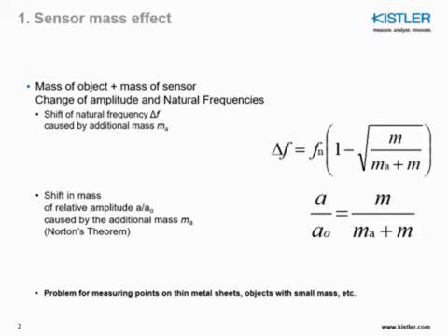You want to understand how much your sensor is going to influence the behavior of the structure under study. The dynamic properties of a structure are dependent on its mass, rigidity, and damping, as well as the way the sensor used for measurement is being attached to it. If the mounting of an accelerometer applies some additional mass to the structure, these dynamic properties can change.